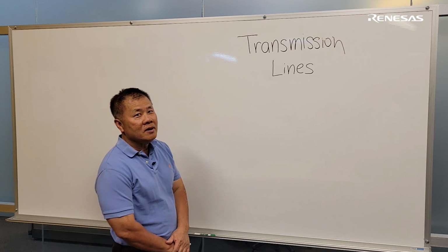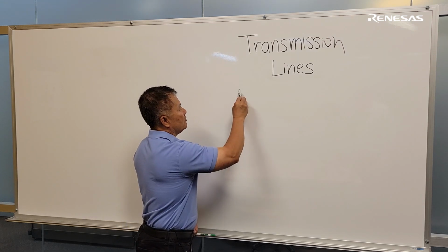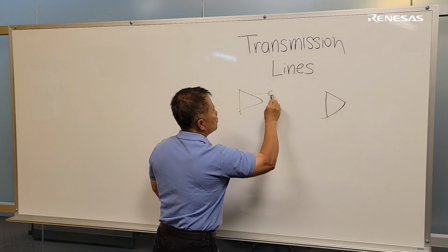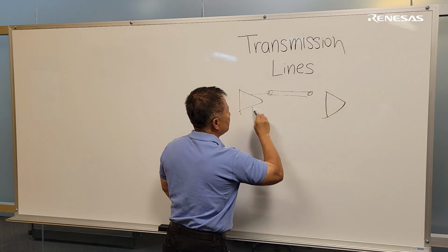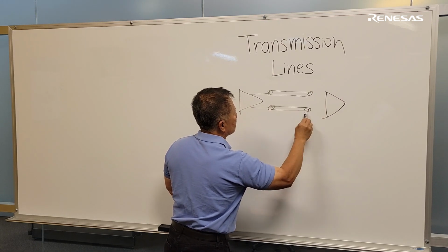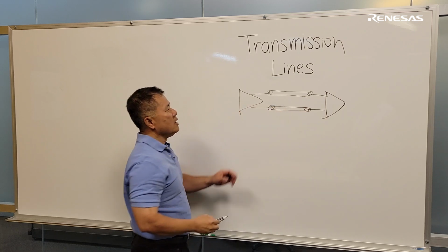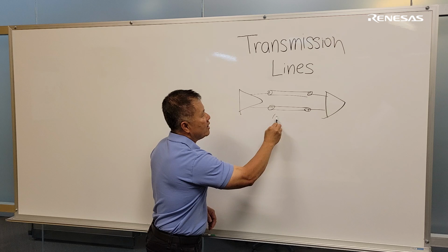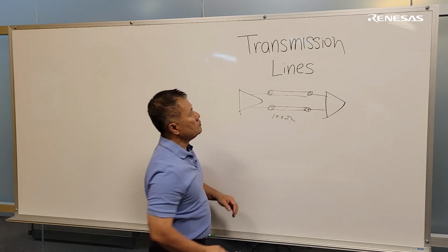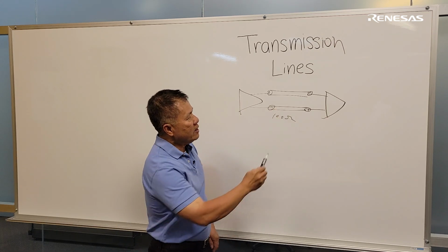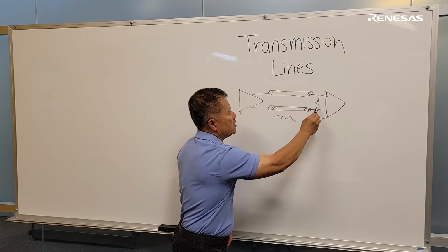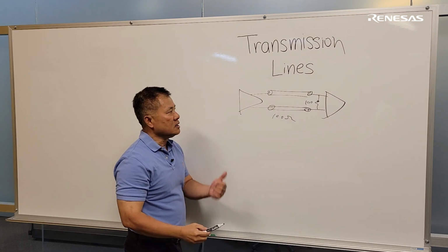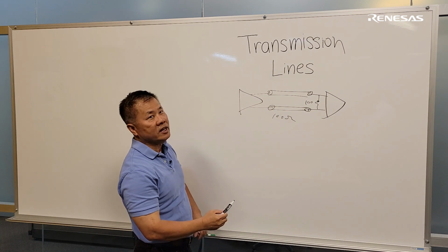For example, for LVDS interface between LVDS driver and LVDS receiver through transmission line, this transmission line is a controlled impedance of differential 100 ohm. And we need 100 ohm termination, match load termination, to match this transmission line. That's a simple termination for LVDS.